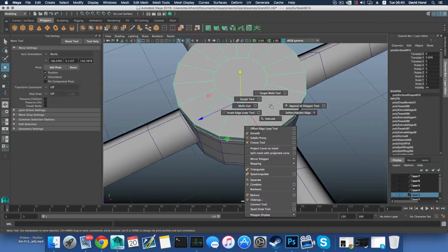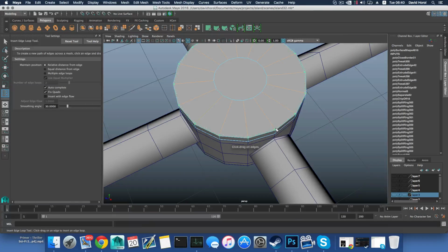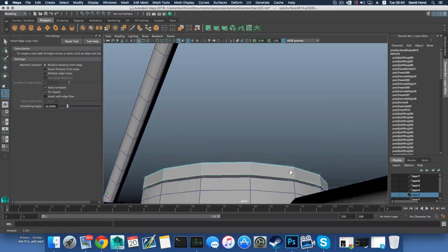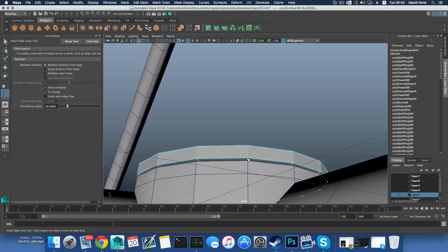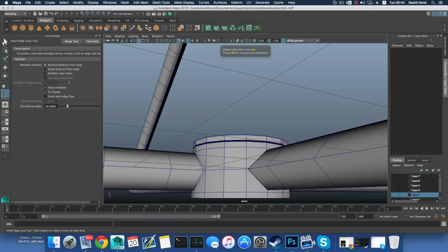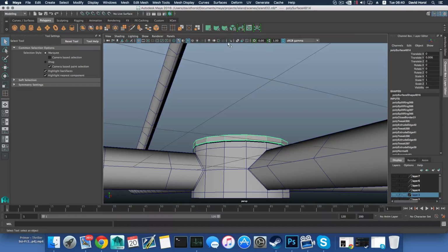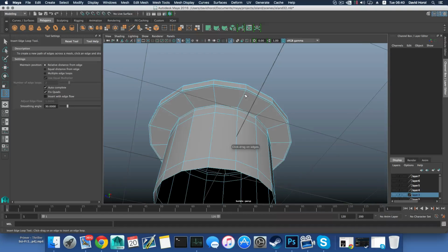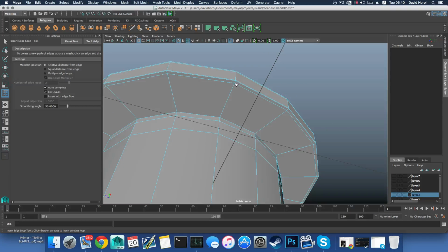So I'm gonna add just a few edge loops here, one here, two on this face that way. I can see this thing, so I'm gonna hit here. I'll press F8 for a second, bring it back to object mode. Let's isolate this for just adding those edge loops that we need. I'm gonna add, well, I added this one.